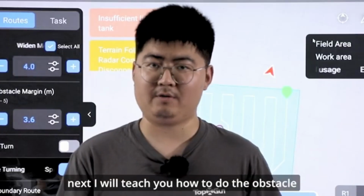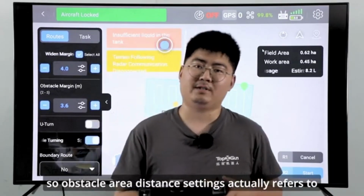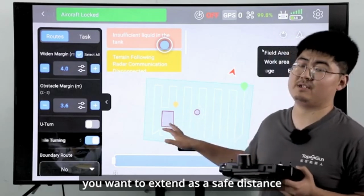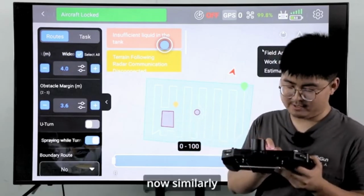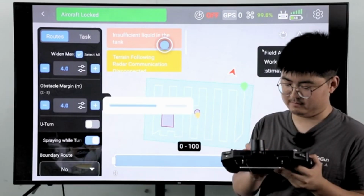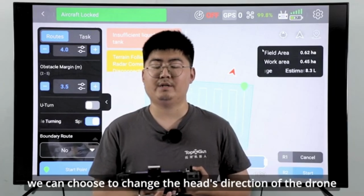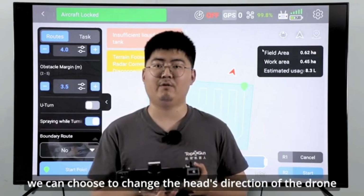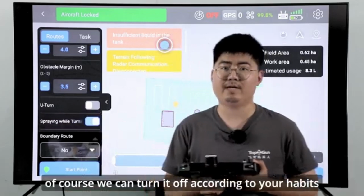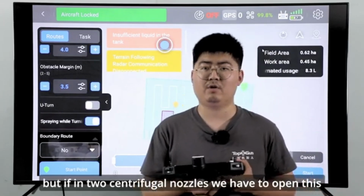Next, I will teach you how to do the obstacle area distance settings. Obstacle area distance settings actually refers to how many meters you want to extend as a safe distance. Similarly, we can fine tune, and of course, we can slide. According to your real scenario, we can choose to change the head direction of the drone. So, it's a U-turn function. Of course, we can turn it off according to your habits. But with two centrifugal nozzles, we have to open this.